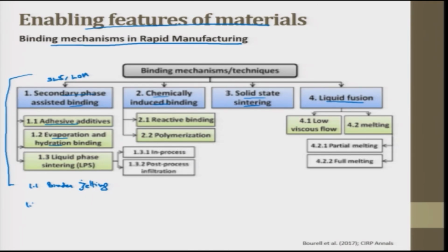An example may be chloroform that can bind biodegradable polyesters and then evaporate during the 3D printing process. The main drawback is the need of a post-processing treatment to improve the part strength in this case.